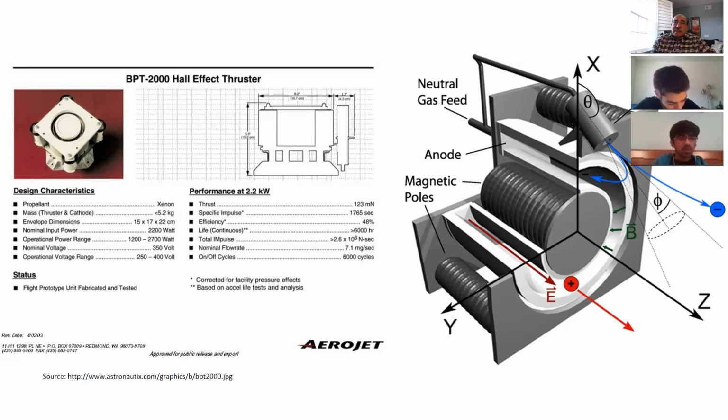And then the second is the design of the anode. It doesn't seem to be a critical component from what you have here, but again, we can look at it and see what temperature rise we would have. It seems like they have certain channels to flow some gas to cool it, or maybe it's cooled enough by the flow of the gas inside. But at least we understand what the thermostructural conditions are with that. If it is not critical, then we just leave it aside.